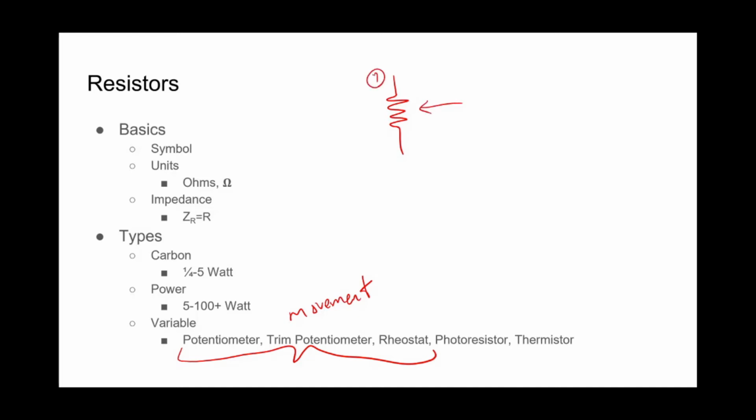So you'll typically see them in 3-pin packages. So it's pin 1, pin 2, and pin 3. To be safe, check the data sheet. Just like wire has a natural resistance along its length, the longer it is, the higher the resistance. The further down this wiper travels, the larger the resistance between 1 and 2. The resistance between 1 and 3 will always be the same. Let's say this is a 10K ohm potentiometer. That will always be 10K between these two points.